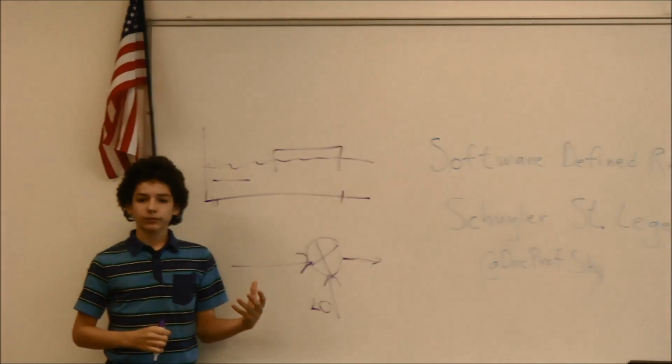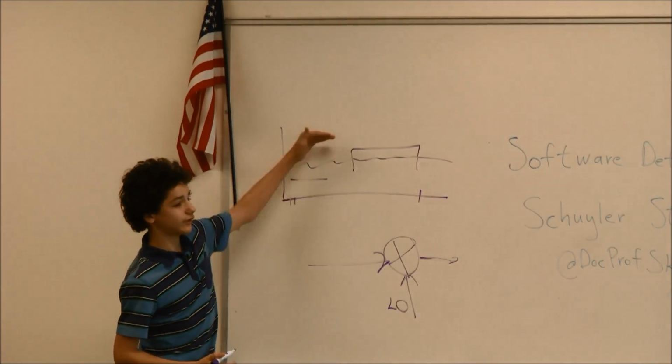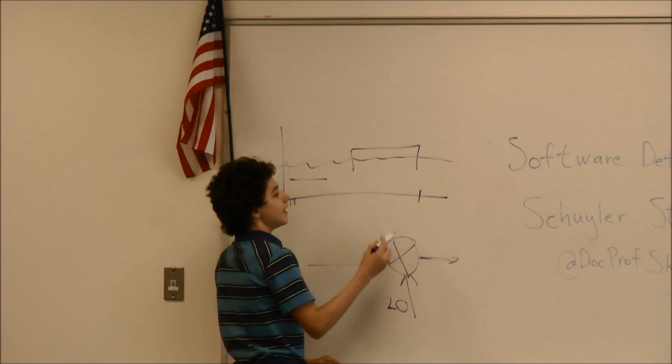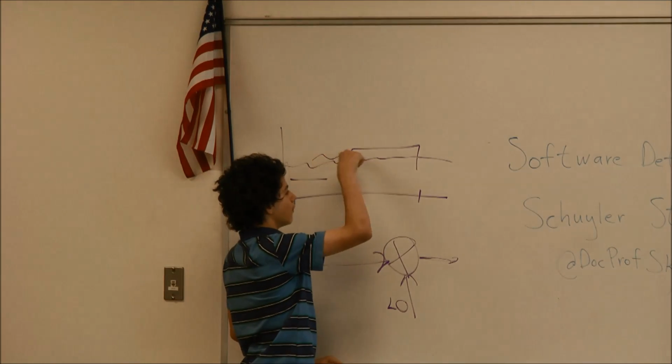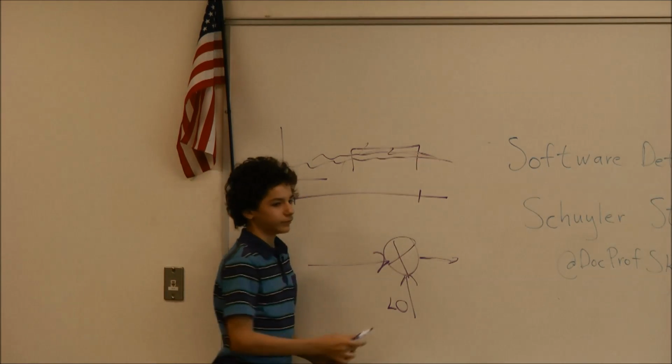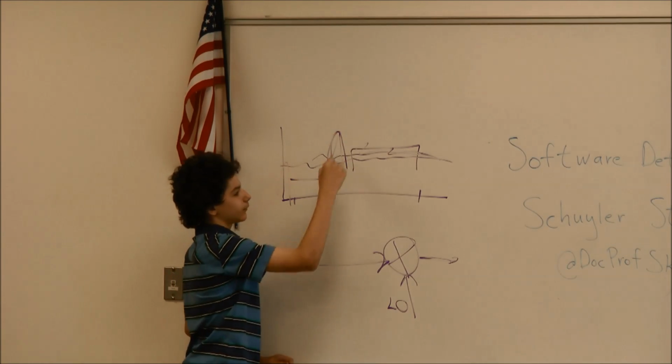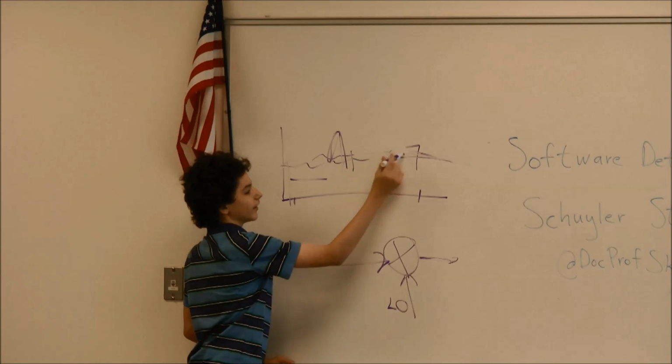So your Wi-Fi router might turn up the gain internally so the signal gets boosted. The problem is that when your microwave comes along, it will raise the noise more, but it might also just blast over the weaker signal. But let's say it goes up here and puts out stuff and it doesn't go over your Wi-Fi signal.